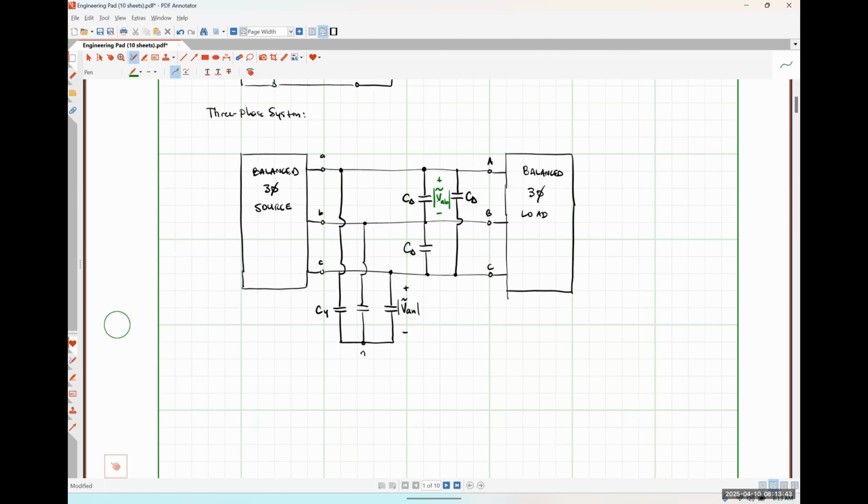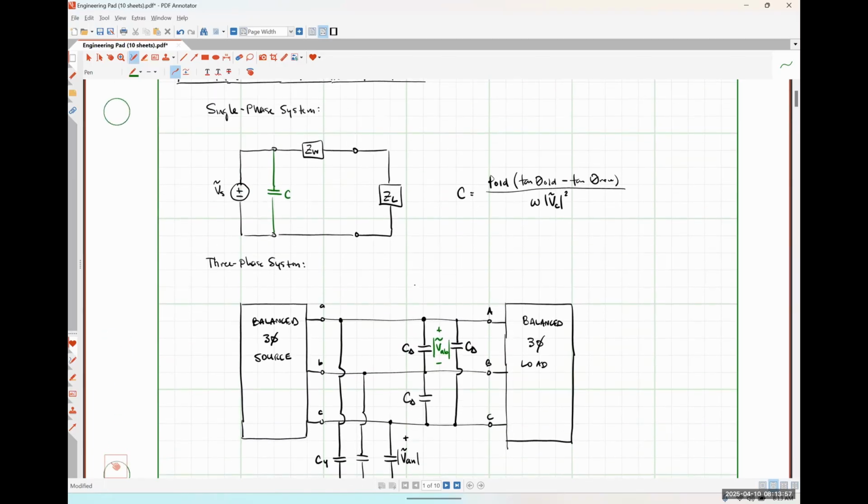All right, before we get into working any example problems, because we've already done the overwhelming majority of the legwork in a single phase system, the one thing that I want to make abundantly clear is that in order for us to apply this equation for C from our single phase relationships, the only thing we need to change is to make sure that we're looking at P old on a single phase basis. We are choosing a capacitor that will correct a single phase of the system and then just adding the two other identical capacitors to correct the rest of the system, right? So we are largely going to approach this on a single phase basis. To see what I mean, let's look at your in-class assignment problem number 1. Okay.